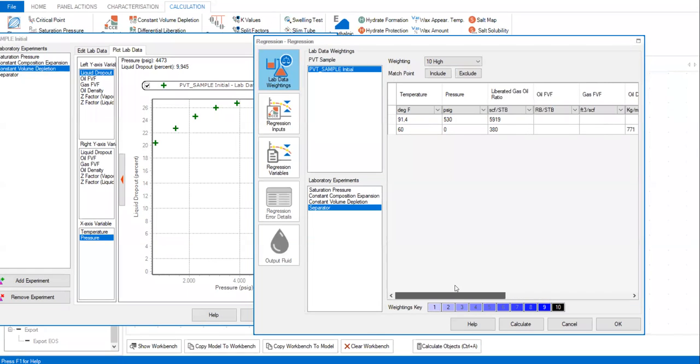Again, this is very important. At this stage, we need already to have a good or relatively good match for the first stage GOR and liquid phase density for the oil. If indeed you have, and of course, right now we have a relatively good match for the GOR and the density, we can use these two values as anchor point.